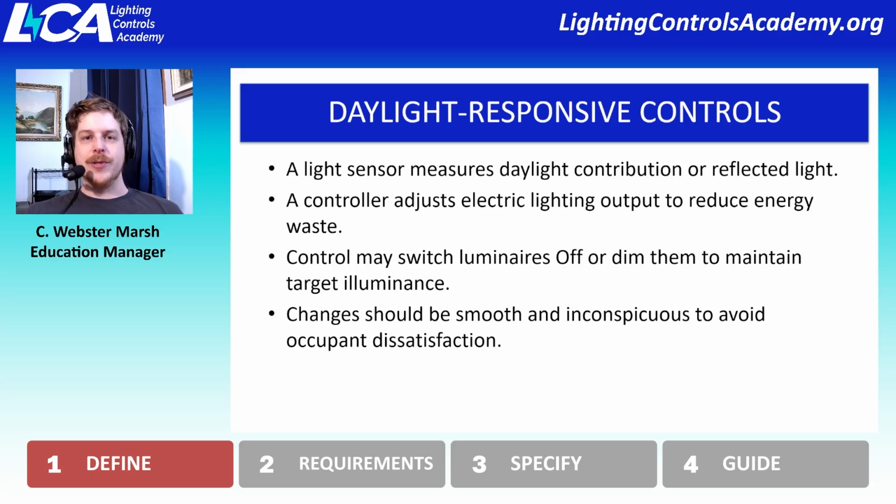is a better way of approaching adjusting the lighting in response to the daylight contribution, and in some cases even leaving fixtures at a little glow to make them look like they're still on, which they still are on, but that way people don't get distracted by fixtures shutting off, especially if you have a big troffer that takes up a huge amount of space. If the big troffer stays on at a glow, it'll still appear to be functioning for the space, and people don't have to worry or hover over that fixture.